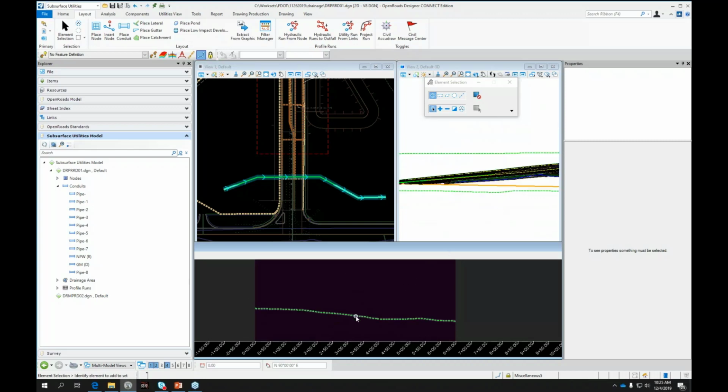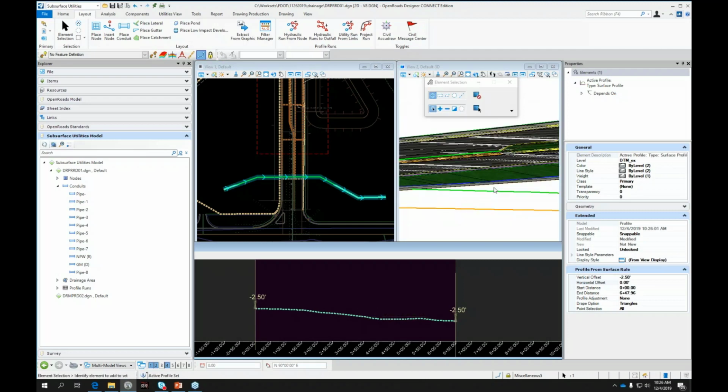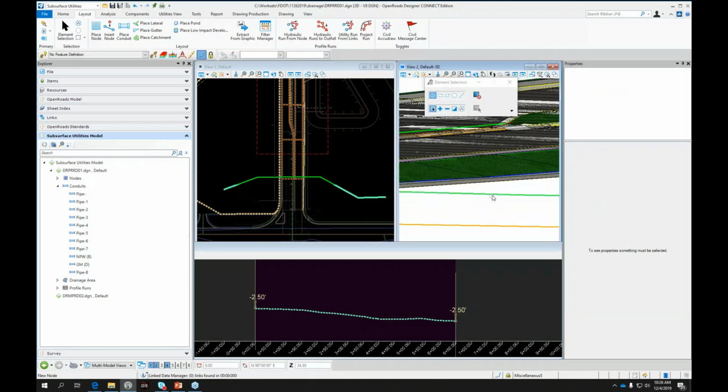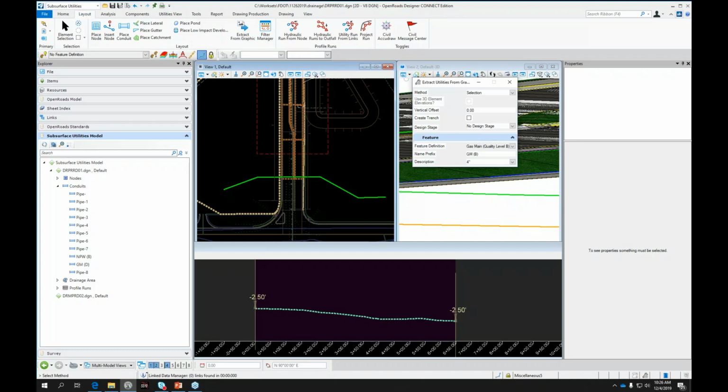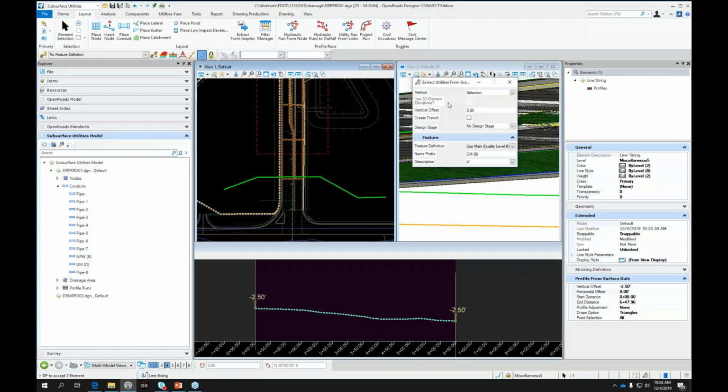And as soon as I make this active, it's going to draw a 3D line out there for me. Now, right now, it's just a 3D line on the miscellaneous 5 level. So this is where you would want to make it actually a utility. So again, let me select it first. And now here, the actual elevation of the object. It says select the surface or reset for the active terrain model. And I should have this enabled here.